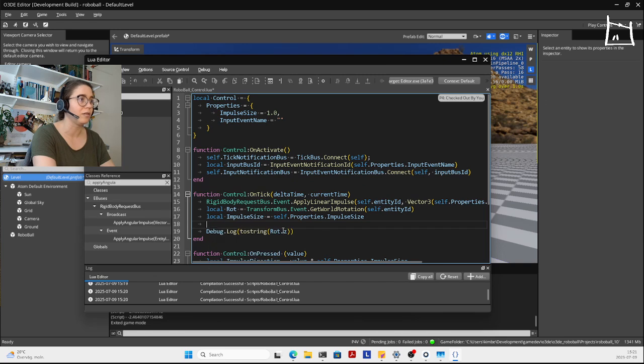And then we are going to do two new values, so like local x new is impulse size times, and then we rotate it with a cosine of the actual heading, which is already in radians, because you want to apply the impulse size not on the world coordinates but on the body fixed coordinates.